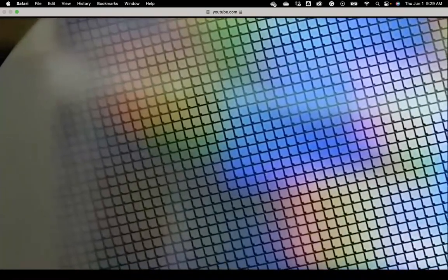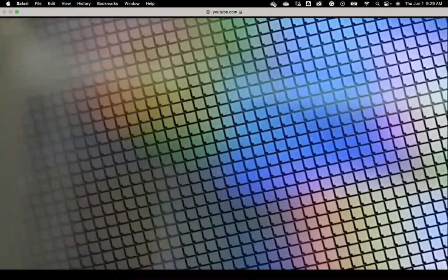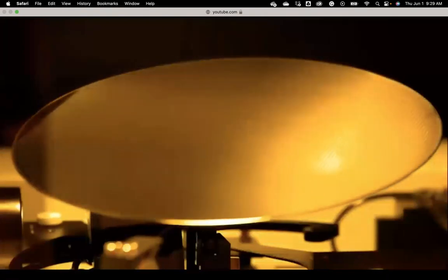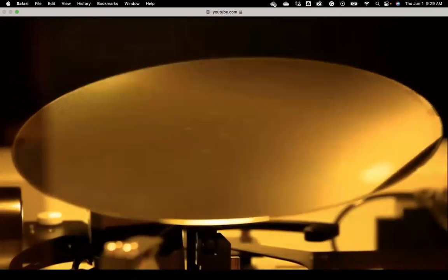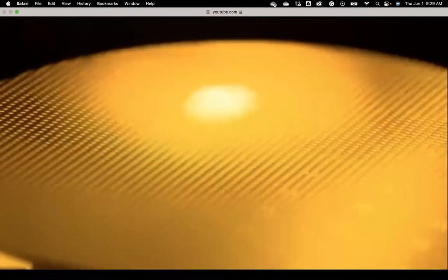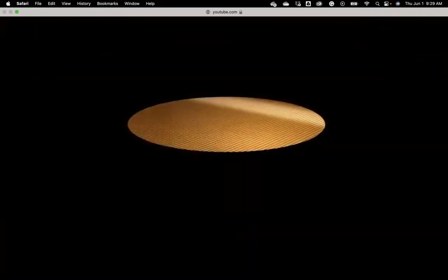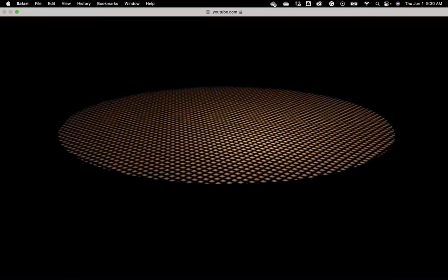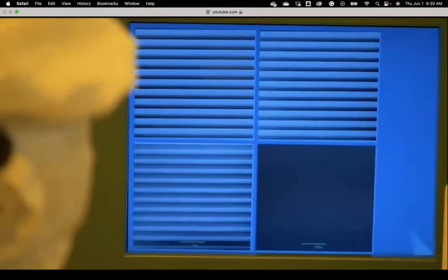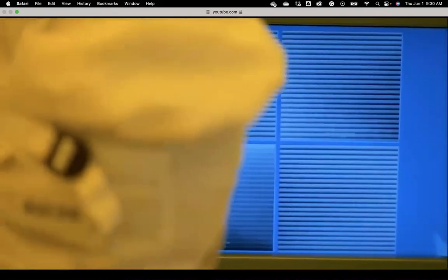Depending on the size and type of chip, the wafer will now contain anything from several dozen to thousands of chips. Individual chips are usually sawed out of the wafer. The chips are not lined up flush with each other on the wafer because tiny parts of the wafer splinter off during the sawing process. A certain amount of space, known as the scribe line, is always left between the individual chips. Test structures are also integrated in this space between the chips and used to take measurements immediately after production. These test structures are destroyed during the sawing process.